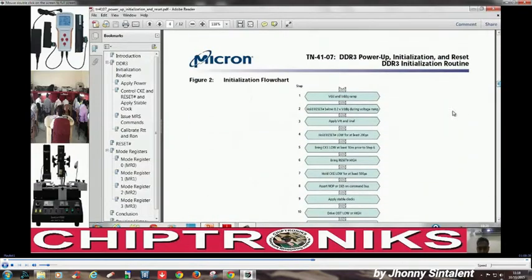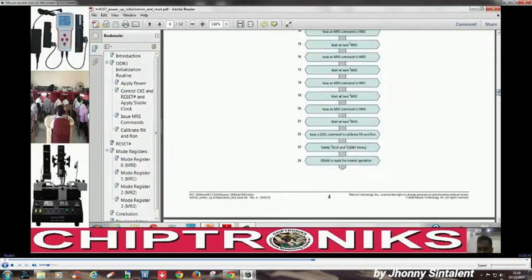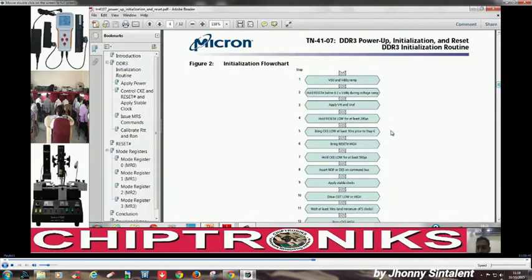See here in this data sheet, there are around 24 steps before a RAM is powered on. And what are the important sequences? One is VDDQ, VTT and VREF. We have already talked about that every RAM requires three supply voltages, VDDQ, reference volt and VTT volt, in order to operate.